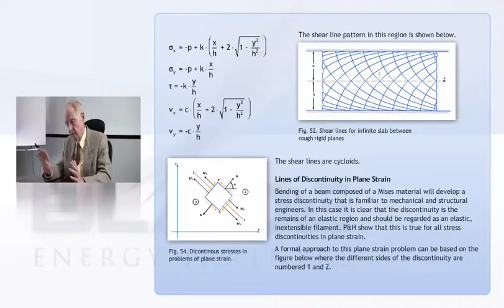And in the limiting case, and nothing happens on this problem until the limiting case, you get sliding at the neutral axis, halfway up, and one part will slide on the other. That can be looked at if you know what really happens with a beam. That's kind of a limiting case of two plastic regions coming together.